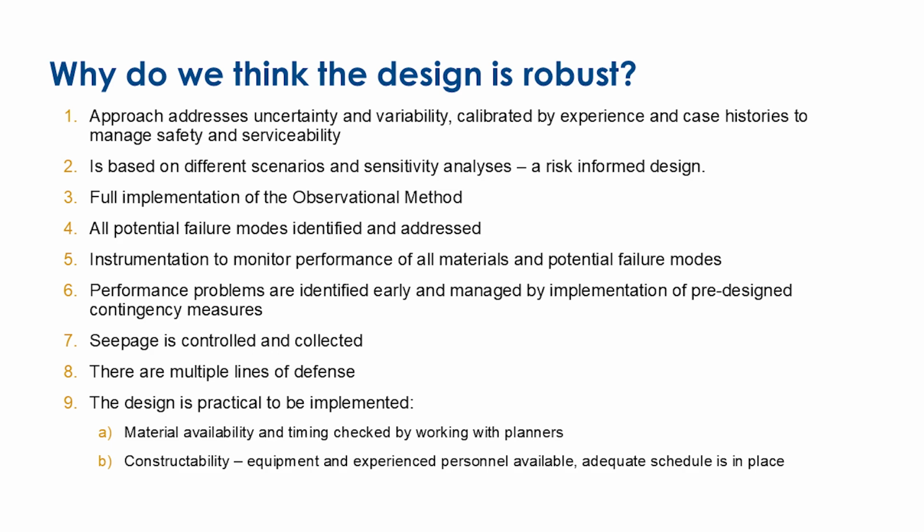We've got instrumentation. And the instrumentation program is not just having the instruments in the ground. It's having them at the right place, properly installed, measured with the right frequency, the data analyzed properly. That's what an instrumentation program is. It's the whole package, right? So seepage is collected and controlled. There are multiple lines of defense. This is a robust design regardless of the approach that you take. Okay, that's what I wanted to say about the robust design.